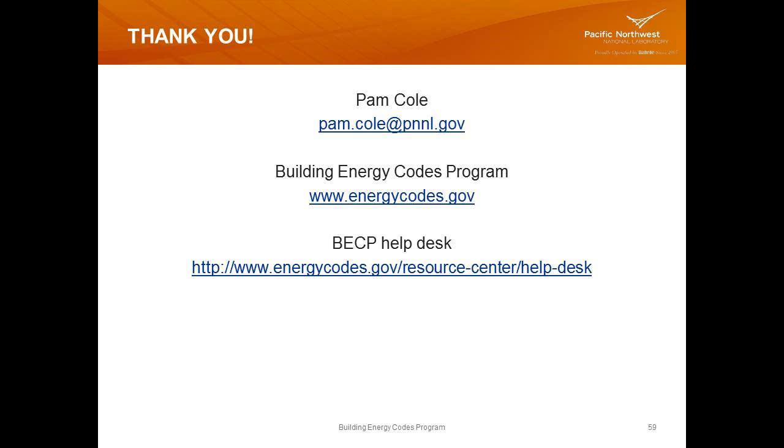Another question that came in, would you enter the square footage of an entire house or just the square footage of the addition in the conditioned floor area? So I think what this is asking is, on the project tab of REScheck, the only time you'd enter every floor, if you have more than one floor that's conditioned, meaning it's heated and cooled, is under the project tab, and it's asking for conditioned floor area.